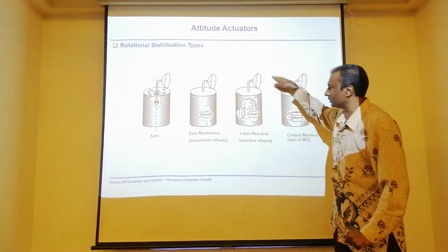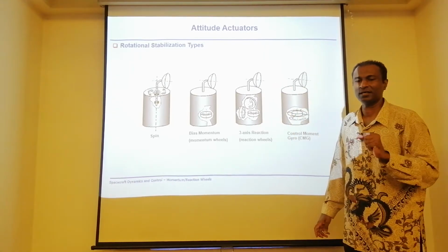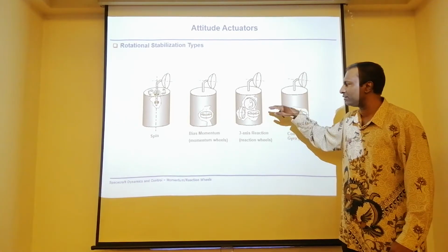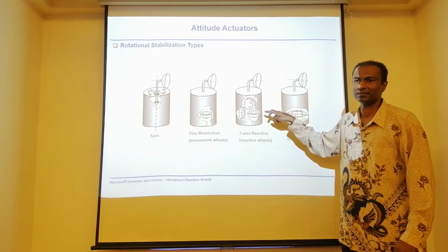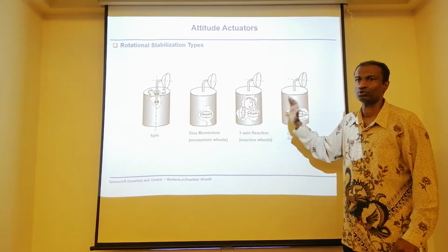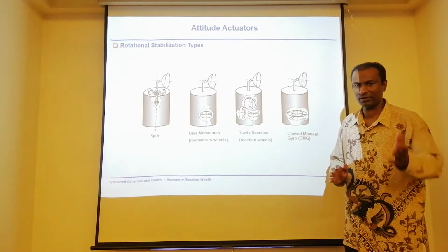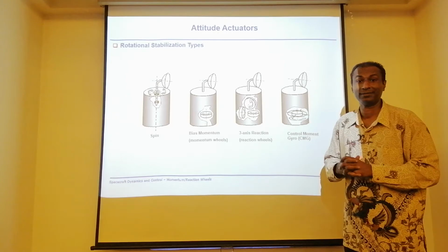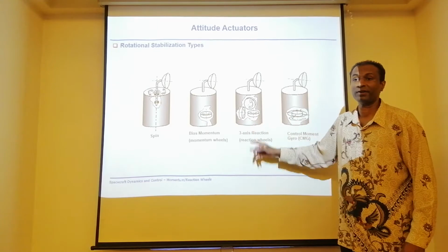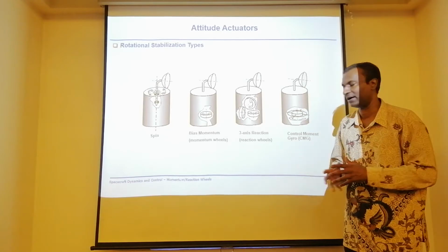Now attention, all those very precise pointing satellites, expensive as well. You will see that more often than not, it will come with 3-axis pointing. Using reaction wheels will be one of the most common options. You want to have an Earth observation mission. Let's say you have calculated all those Earth observation exercises. All those Earth observation satellites, more often than not, will be flying with the reaction wheel, because the reaction wheel will give you a good attitude performance, just like what we have seen before.